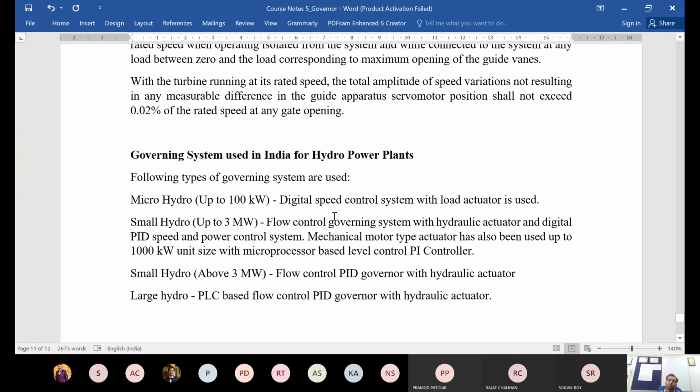So this might be recommended for a small generator up to the 100 kilowatt range, because the control mechanism and the computational infrastructure is more expensive. So you don't change the flow. You don't change the power flowing into the turbine and the power generated. What you do, rather, is that if you have extra power, then you do some sort of load adjustment. That is known as the electronic load controller. We'll look at that in the next class.